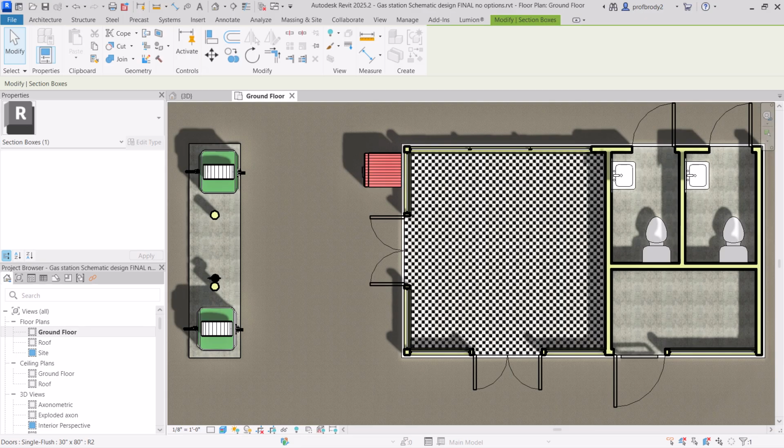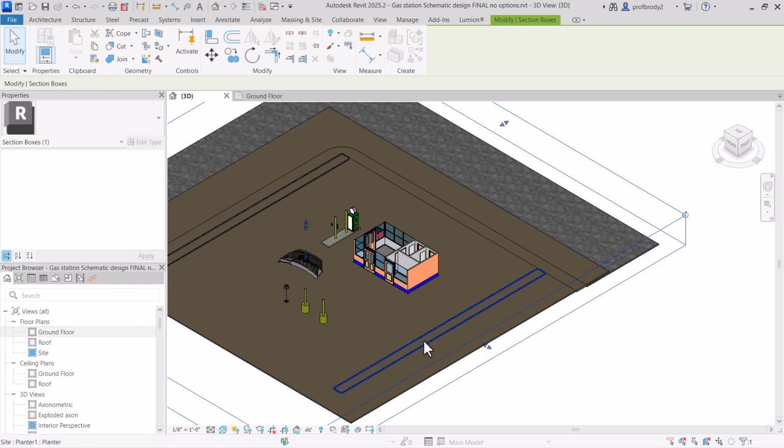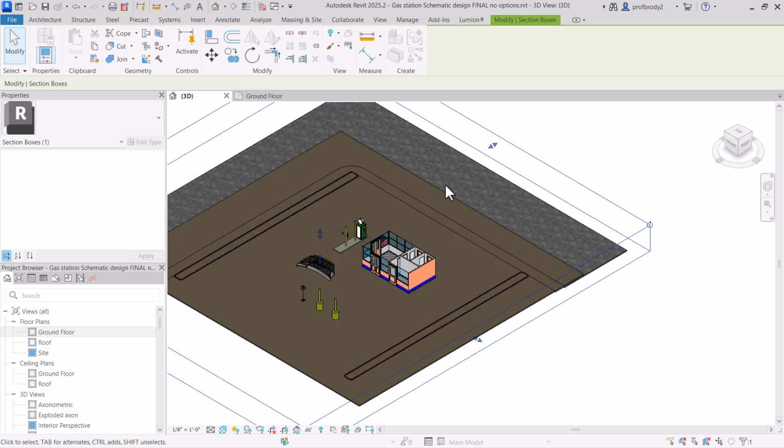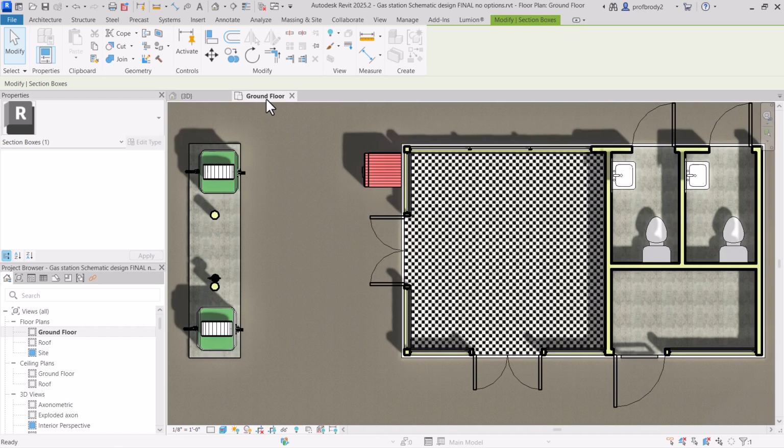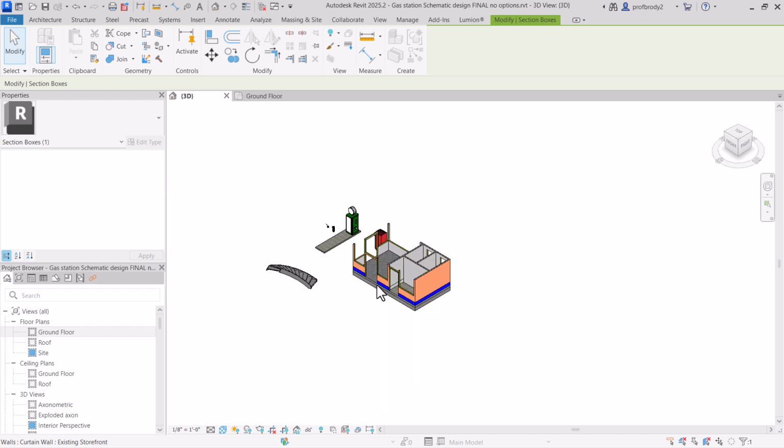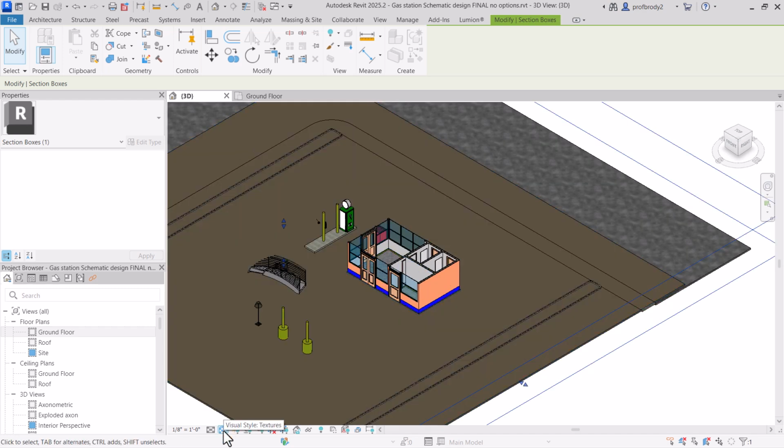The one area where Lumion does not play consistently with Lumion materials or Revit materials is poche. As we saw before, you can change the color of poche using your graphic display options. We fiddled around with that: visibility, graphic overrides, we can override it or use phases. But Lumion takes its settings from the 3D view that you launched it from. It doesn't care what the floor plan is. And like I said before, I launched this and I just have this in shaded mode.